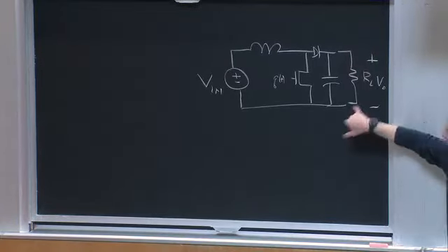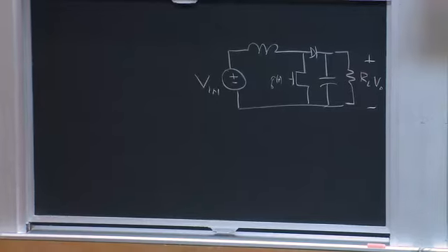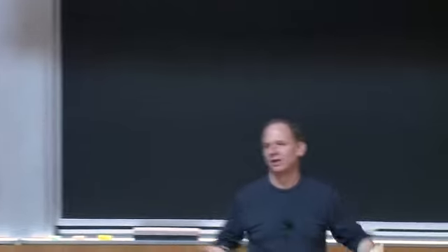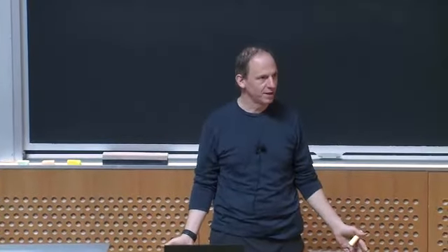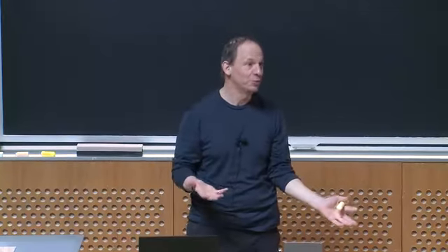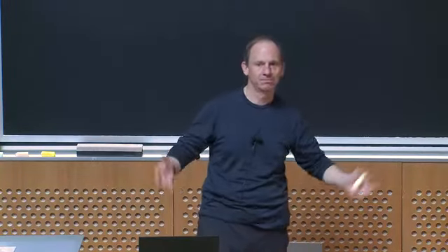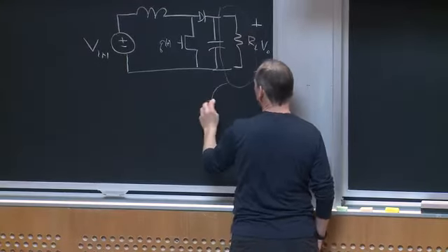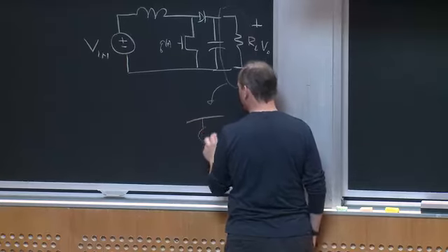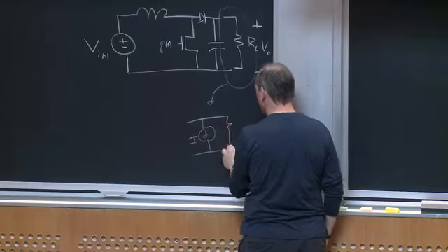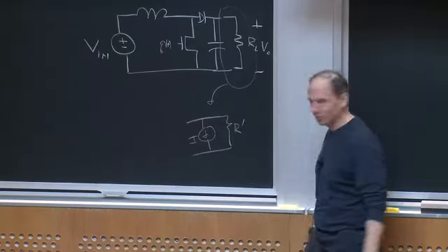Now, by way of an aside, in my examples I usually show a resistive load. A lot of loads are resistive, right? But there's no guarantee that, in an actual application, your load looks like a resistor. It could look like whatever. A lot of loads you might represent as some Norton equivalent, where there's some constant current component and some resistive current component, right?